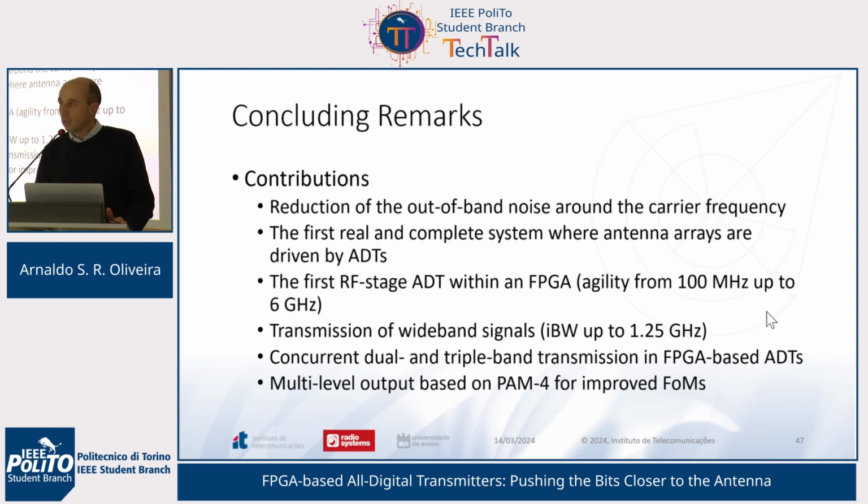We were the first at that time to have an agile transmitter in which the pulse modulation is done at RF, which allows a fine-grained control of the carrier frequency. We were able to transmit very wideband signals. We allowed concurrent transmission, in our case up to 3 carriers using just one all-digital transmitter, and we were able to test successfully with PAM4 transceivers in this scope.